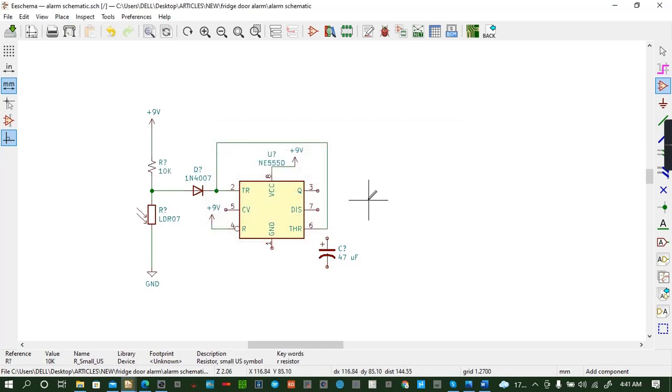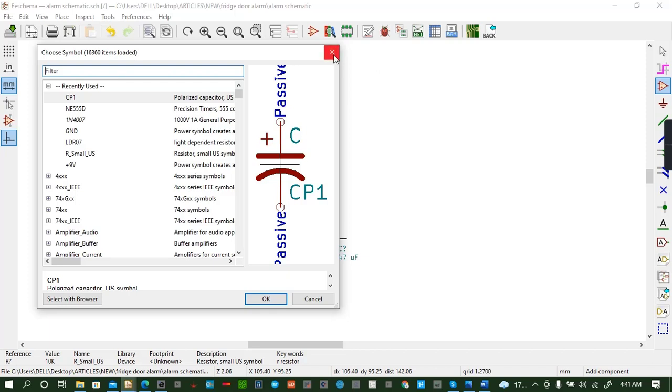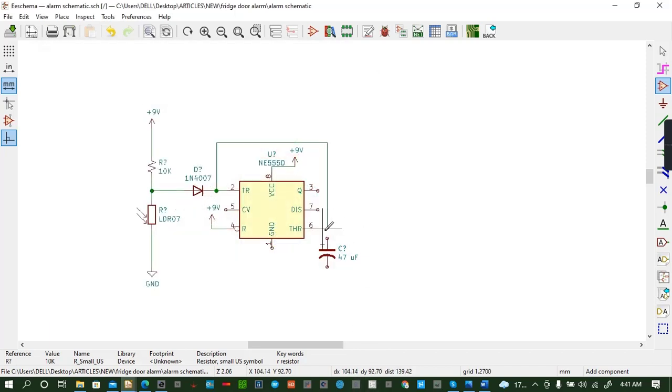And then now we connect this. This capacitor is connected from here to this point. So you come here. You input wire, and then you connect. That one is connected. The capacitor is connected to the ground, so you can copy this by pressing C. Like that. But again, that one is wrong. So you copy. You have to connect with a wire. Like that.